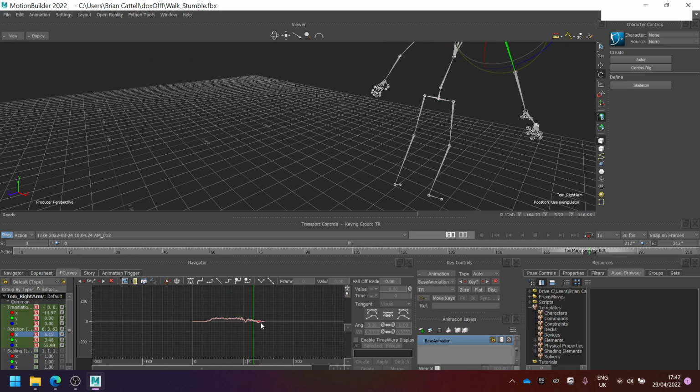So this curve is made up of the multiple keys that we've got from Mocap. And there are controls here for the interface, which is sort of okay, but you don't want to keep going to that button there to make the changes. So I'm going to use the key shortcuts, which is the Alt key, and it's just like navigating the viewport in Maya.